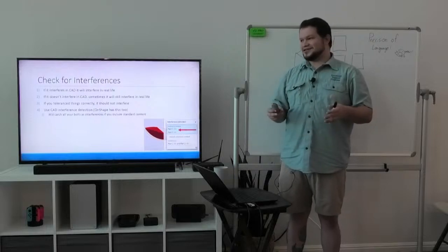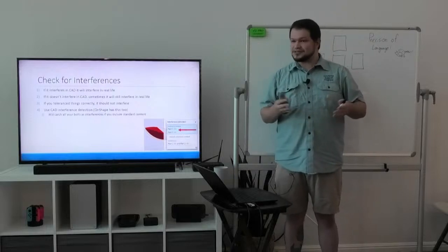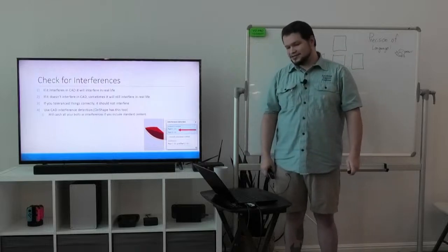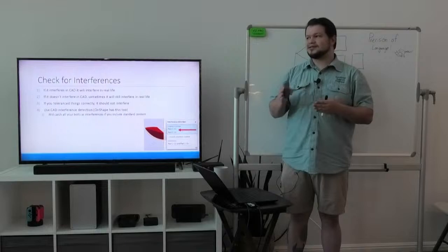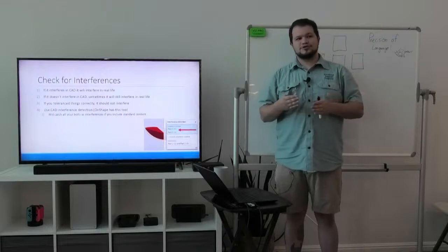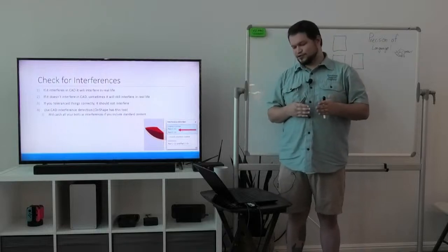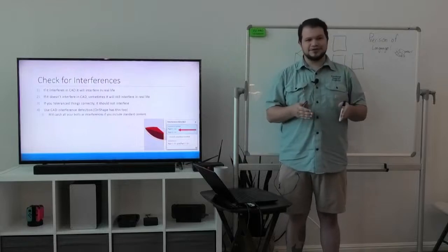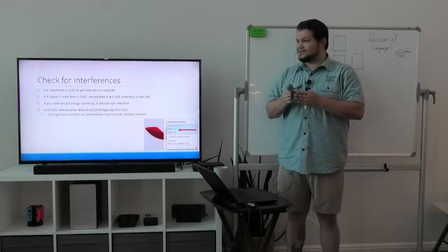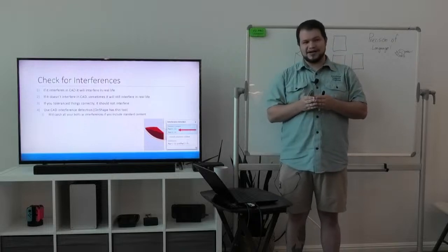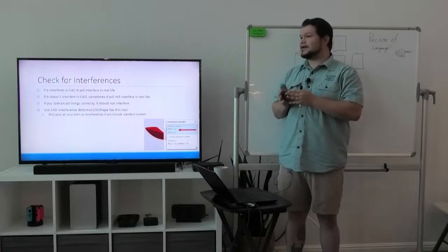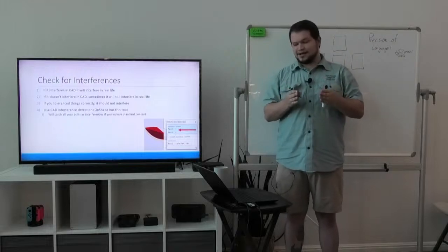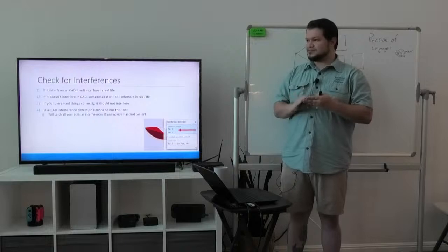It really depends on the tolerances of what you've built it to, the tolerances of your machines that you're making it on. And sometimes you have to make things close fits, and you've made them a little bit too close of a fit than what you would like. So you should have a plan in place for when that happens. If you know that these things need to be kind of tight fit together, you should have a plan for if they are too tight of a fit, what am I going to do? Am I going to redesign it with a different offset and reprint it, or maybe I take just some sandpaper to it?